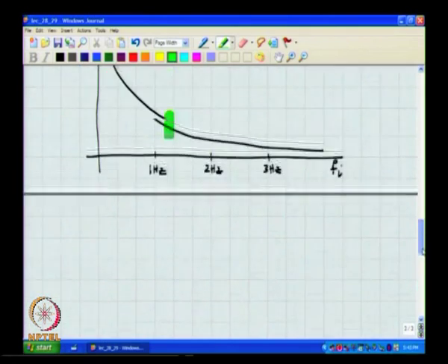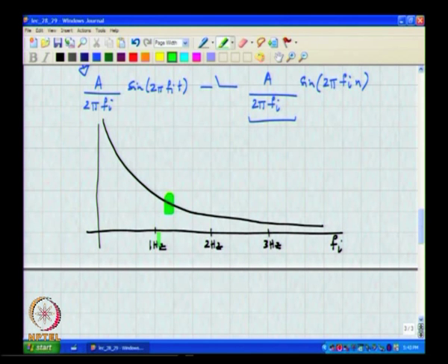And so, to show it on the same picture, the sampling rate corresponds to how many radians in the discrete time domain? 2 pi. So, this is 4 pi, 6 pi and so on. At pi, what is the gain of the NTF? 1 minus Z inverse, it is 2.